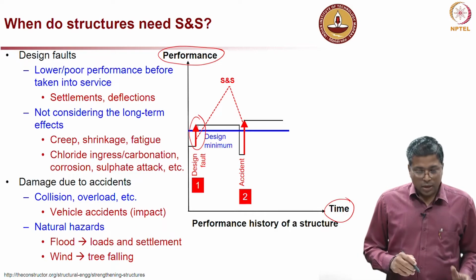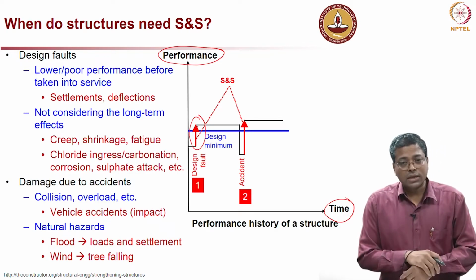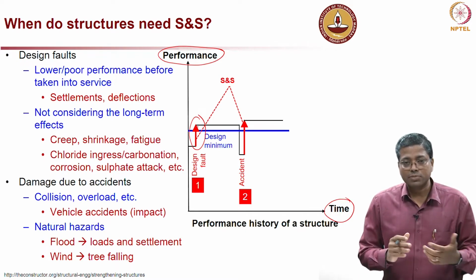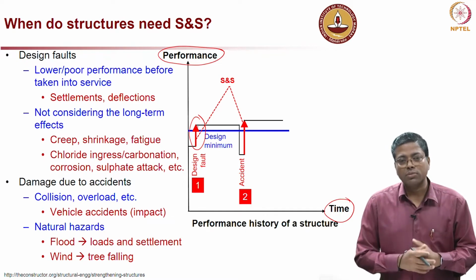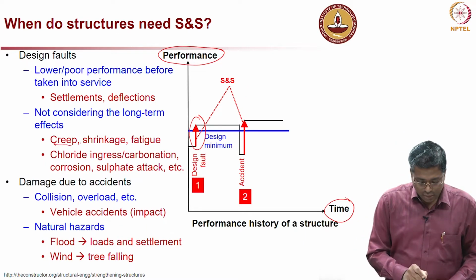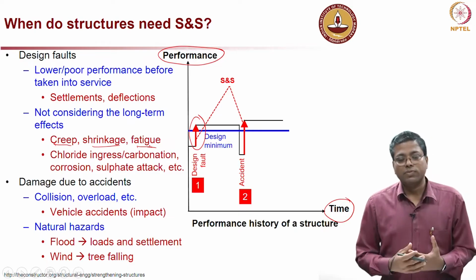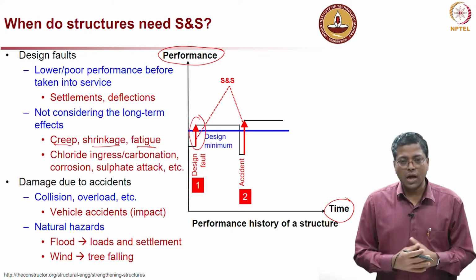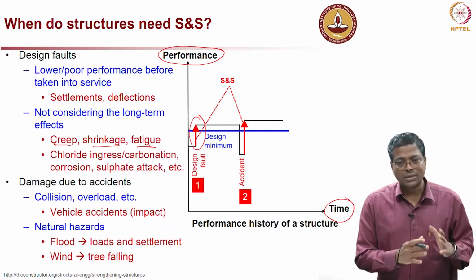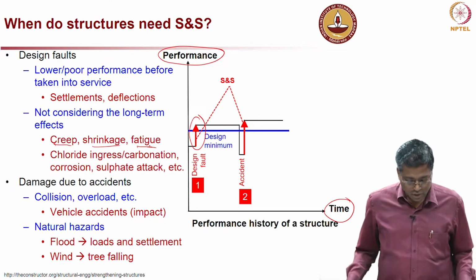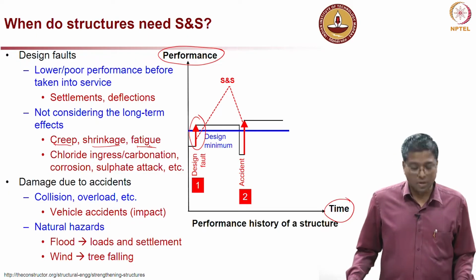And why does faulty design happen? One reason is that sometimes people do not consider long term effects, for example creep or shrinkage, fatigue, etc. The problems because of these will show up not necessarily in the first week or so, but maybe after some time, sometimes even months.